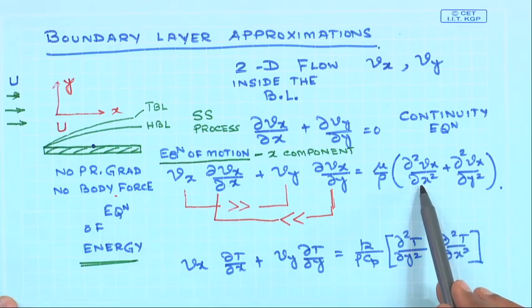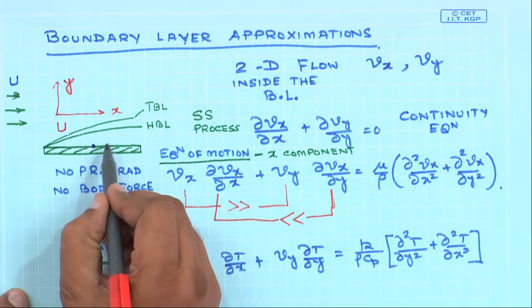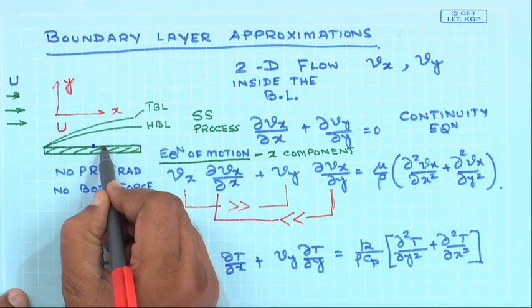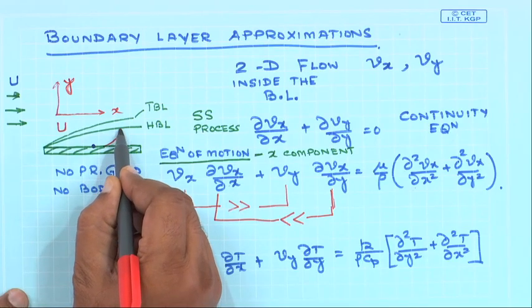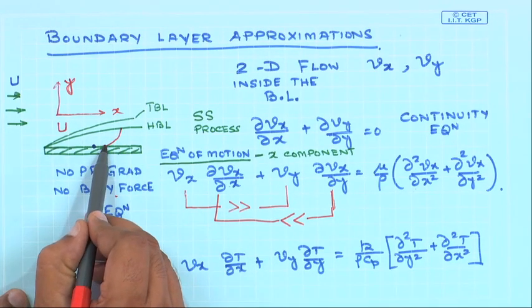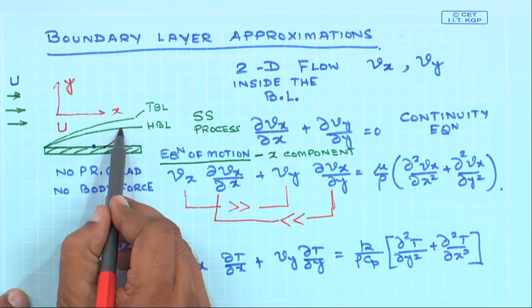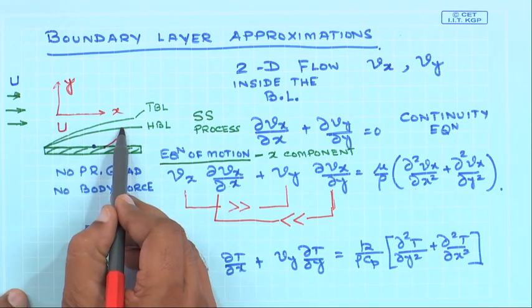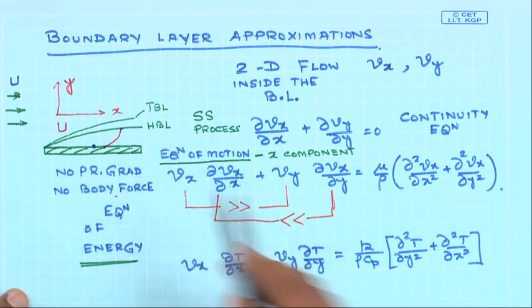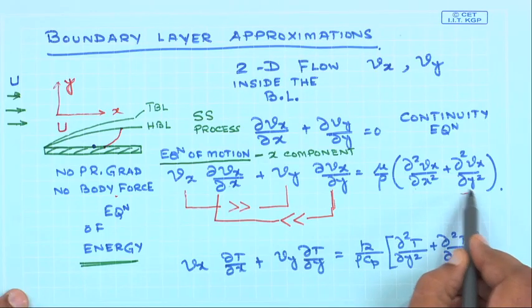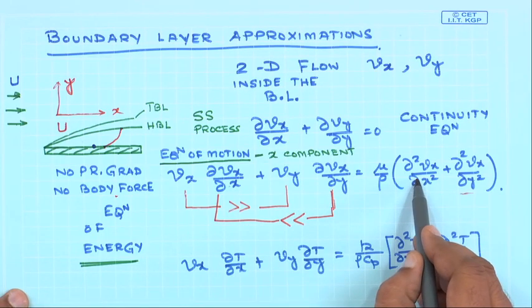This is the transport of momentum because of the presence of viscosity, such that the momentum is transmitted through the layers which are moving at different velocities. So the velocity profile would probably look something like this, where it starts at a value equal to 0 and asymptotically approaches capital U. So this one is the diffusive transport of momentum.